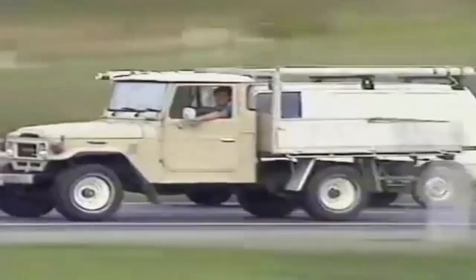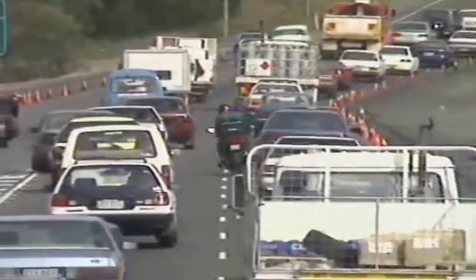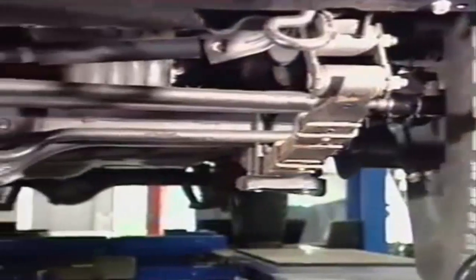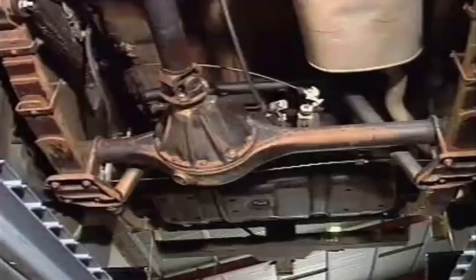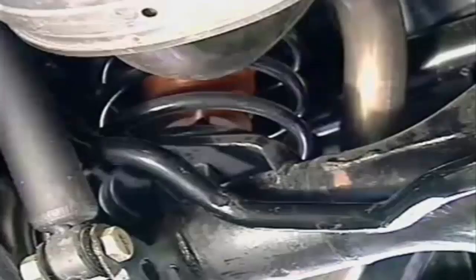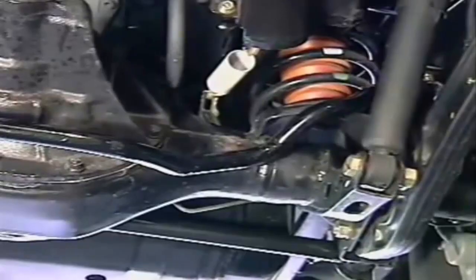Passenger cars no longer use beam axle front suspension, but it is still common on heavy commercial vehicles and some four-wheel drives. Trucks use an I-beam, in most cases located by leaf springs. Four-wheel drives with rigid axles may use leaf springs for front and rear suspension. Coil springs may also be used for front and rear. And as with other beam axle designs, a lateral rod and control arms must be used for location.